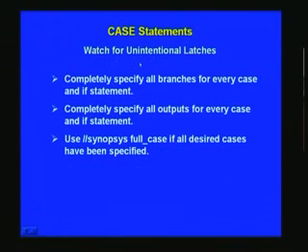And you have to be very watchful, otherwise you will be creating unintentional latches as such, which we have already considered. Therefore, in order to avoid this, completely specify all branches for every case. At every case statement, for every possibility, you have to consider it wholly. So also for if, else if statements, you have to consider all the possibilities. Don't leave anything to chance. Otherwise, you will get into trouble later on.